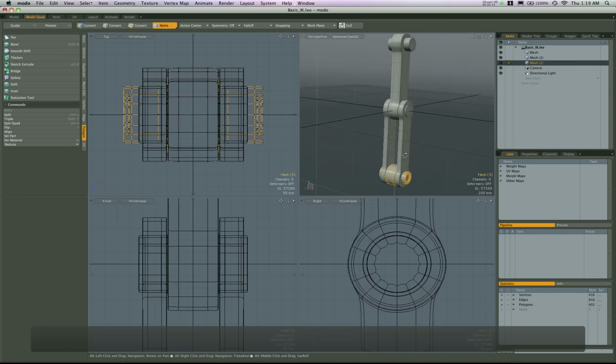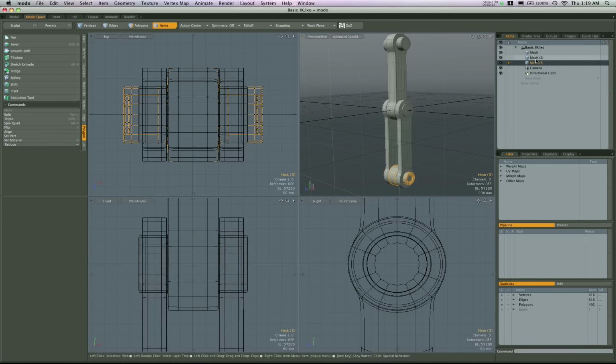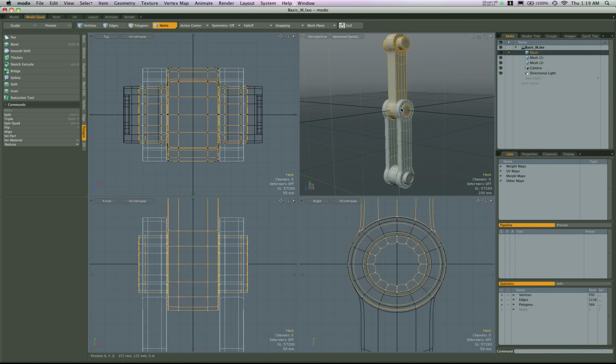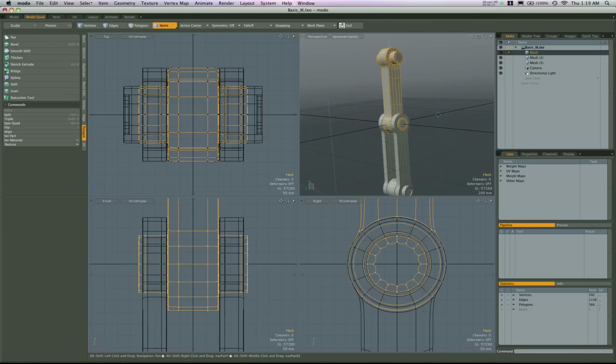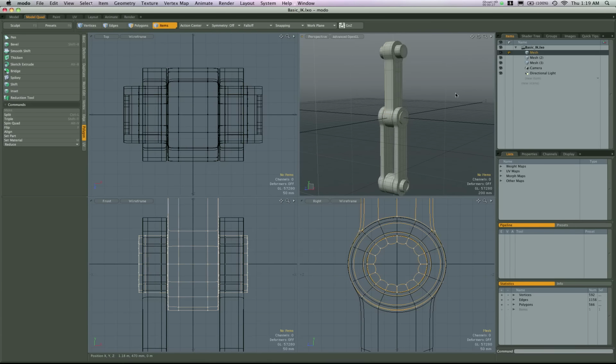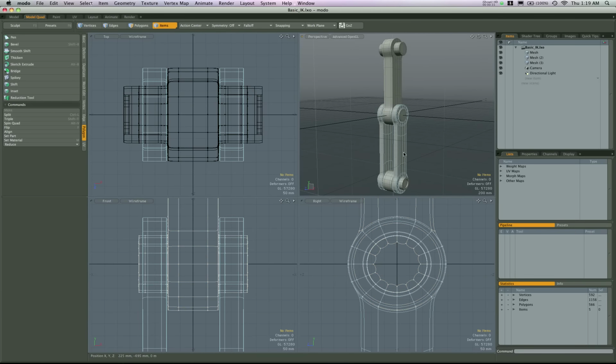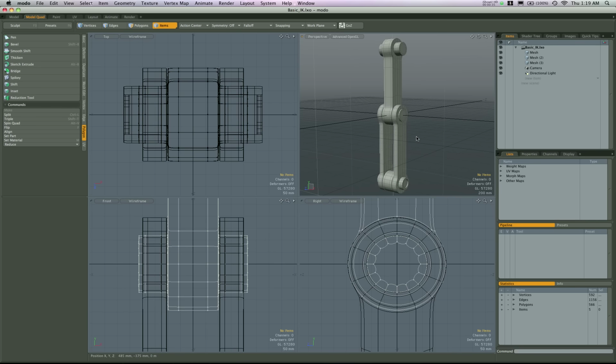And you can see that I have essentially three mesh layers. I have this bottom joint where the foot would be hooked up. I have this middle joint, kind of a lower leg, and then the upper leg here. So we're going to take these three pieces and rig them up together so that we can move them around, and also that we can set up an IK set on them.